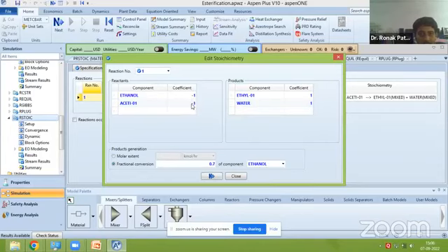Here you can see the minus sign because they are reactants, which are going to be consumed over a period of time. So by default, if you write 1, 1 over here, Aspen will consider -1, -1. On the product side, we have ethyl acetate and water, which will have a positive coefficient because they are products. I have selected a fractional conversion of ethanol of 0.7, because R stoic does not consider the reaction thermodynamics. Whatever fractional conversion you give, 0.2 or 0.5, without checking the thermodynamic feasibility, it will give you that conversion.